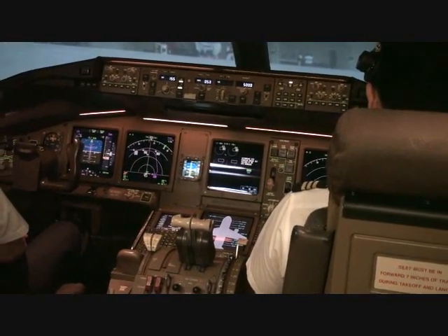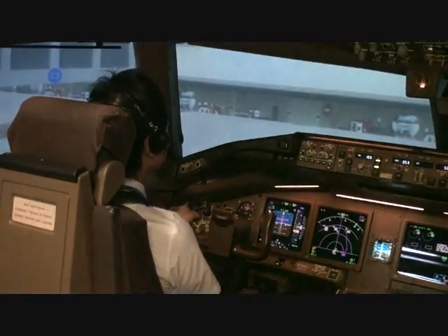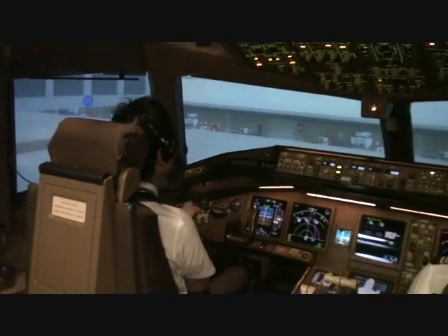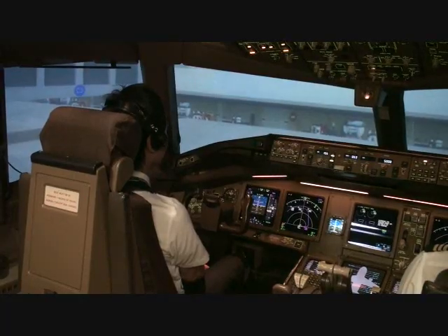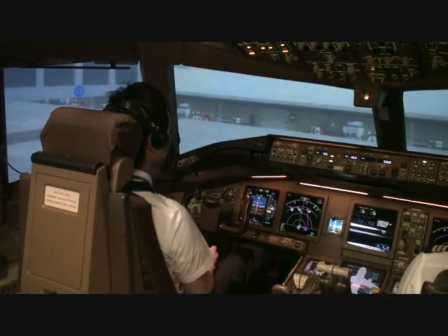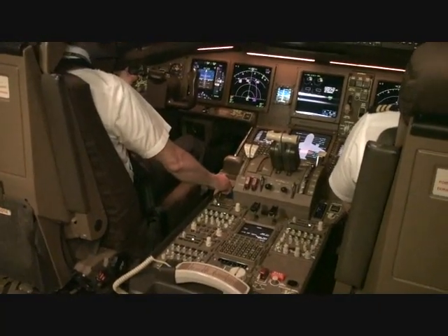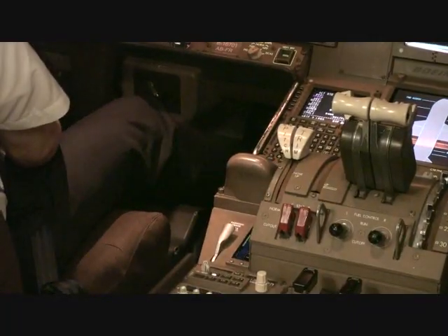Ground handling personnel establish communications. CM1: Hello ground, we are clear for pushback and start, runway 05 right. Roger Captain, please release parking brake. Caution, do not hold or turn the nose wheel tiller during pushback. This can damage the nose gear or the tow bar.